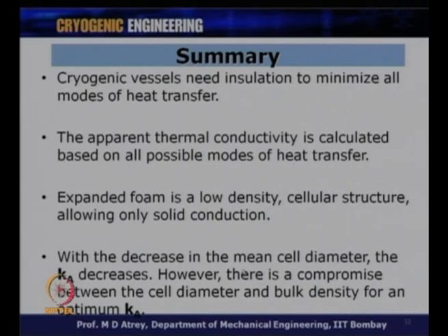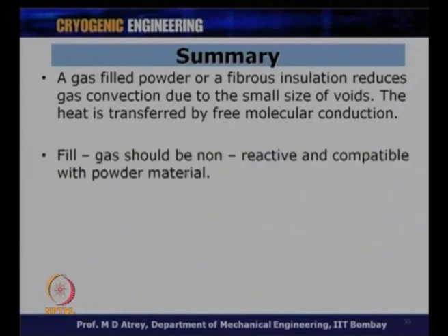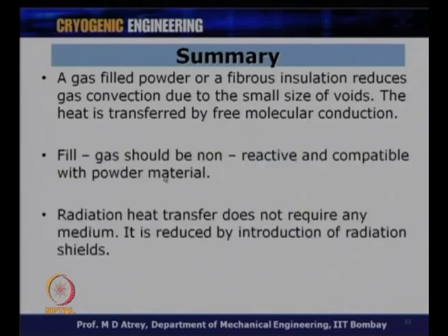How does that come into the picture? A gas filled powder or a fibrous insulation reduces gas convection due to the small sizes of voids. So, we have very small particles sitting over there in which there could be gas, and this will effectively reduce the apparent thermal conductivity from 30 to 55 milliwatt for expanded foam to around 20 to 35 for the gas filled powder case. The heat transfer happens because of free molecular conduction in this case. The filled gas should be non-reactive and compatible with the powder material.